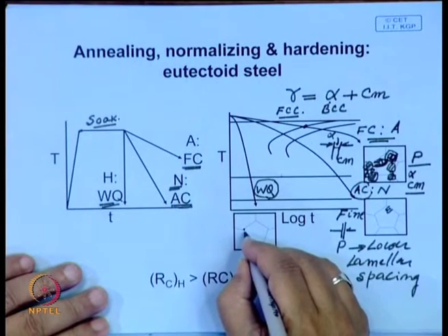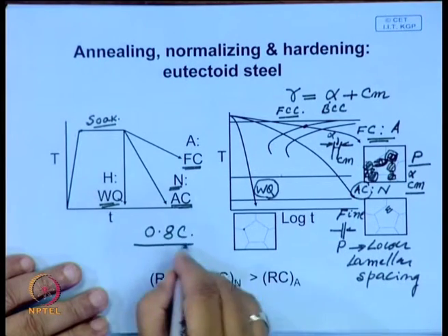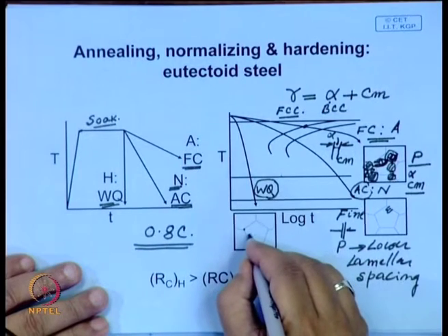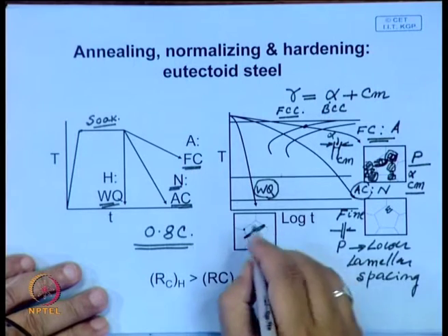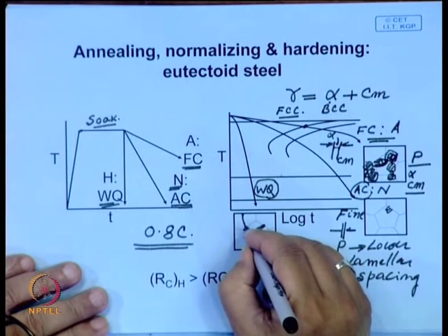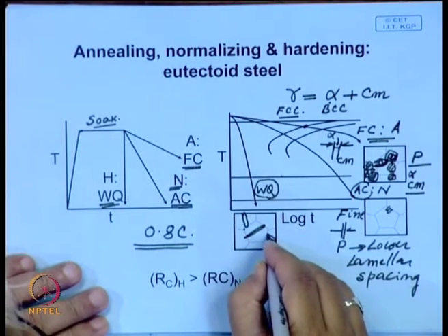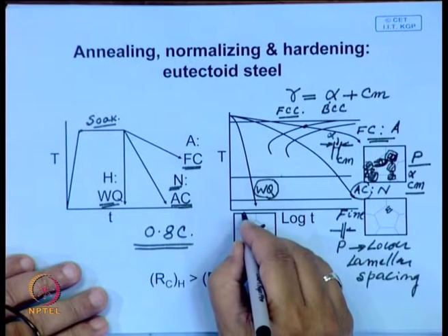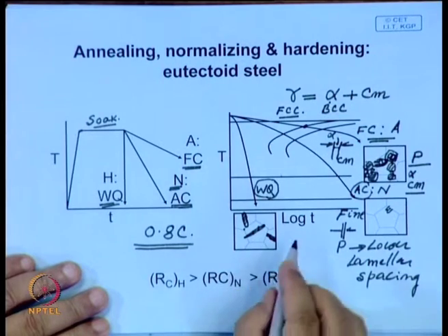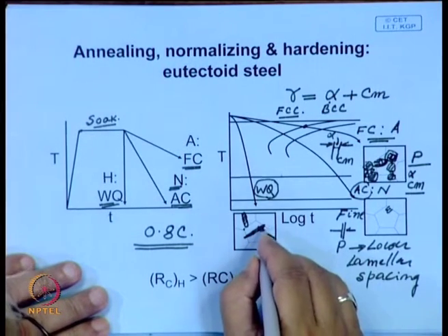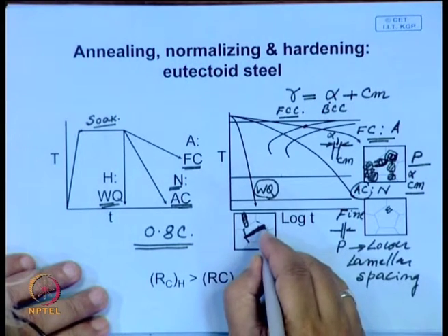We looked at its characteristics, and in the case of a eutectoid steel the carbon content is quite high, 0.8% carbon. So, here what you expect is a plate type of martensite. These martensite plates will form, and these plates will be made up of very fine micro twins, which will not be possible to detect or see under an optical microscope. And when these plates grow, they cannot cross this boundary. If it starts from here, it will end at the boundary.